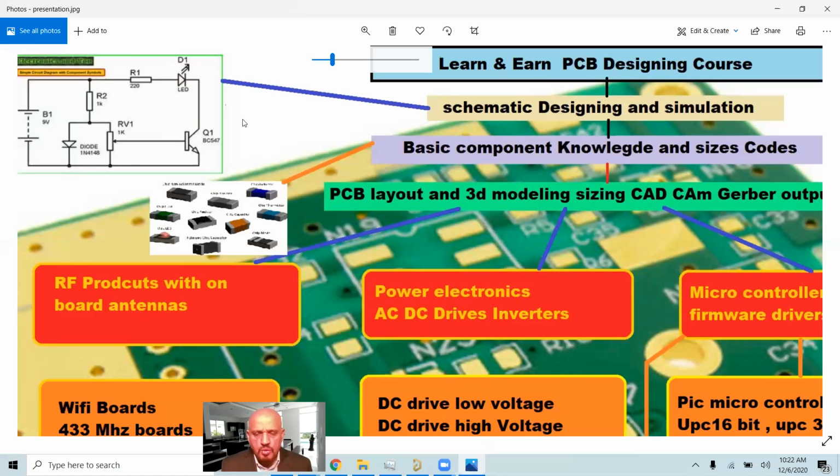What happened was that Sony decided that the quality of the color picture was not too good, it was blurry, and the colors sometimes overlapped. The reason was that three different beams were coming and striking the screen. When they strike and overlap with each other, it's not necessarily 100% focused. On the edges they are not focused. If you're young, you have never seen this, but if you ask your parents, they will say the sides were always blurry and dark, and the center was always bright, because the beam moves like this, and the curvature is made to make the distance travelled together on this side.